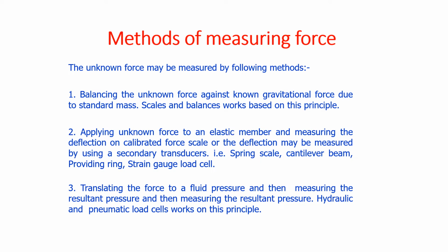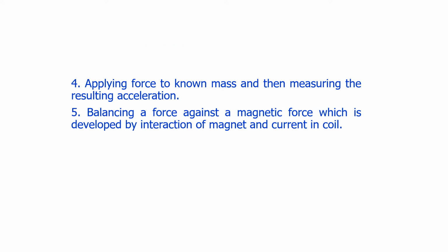Unknown forces can also be measured. The main aim is to measure the unknown force. For a known force we need not worry, as we can calibrate it. Only for calibration we can have that topic for known weight. The unknown force can be easily measured by various balancing scales, cantilever beam, proving ring, strain gauge, and load cell. Many devices and load cells are there to measure the force.